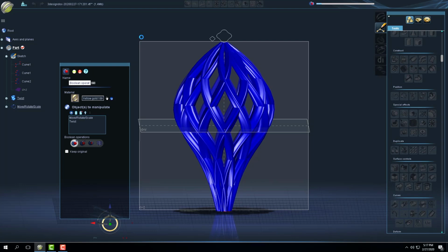Yeah, when you're doing Boolean operations, there's actually some pretty incredibly complex math going on. You can have Boolean errors. So things that exist in the exact same space in the CAD software, most of the time a CAD software may be able to compensate for it, but in a lot of cases the Boolean may fail. So that's one of the reasons to do a slight scale just to make sure.